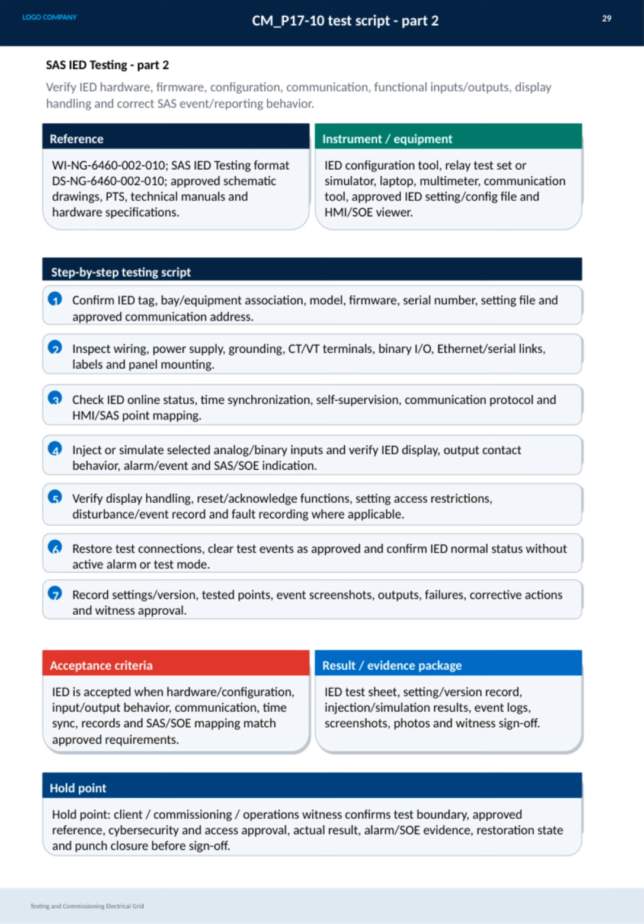Finally, the evidence package, including test sheets, logs, photos, and sign-offs, is compiled. A hold point ensures that client and commissioning teams review all results, cybersecurity measures, restorations, and punch list closures before final sign-off. This meticulous approach guarantees the IED's reliable operation in the grid.